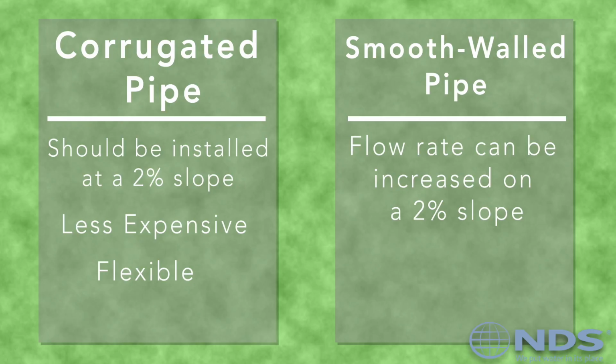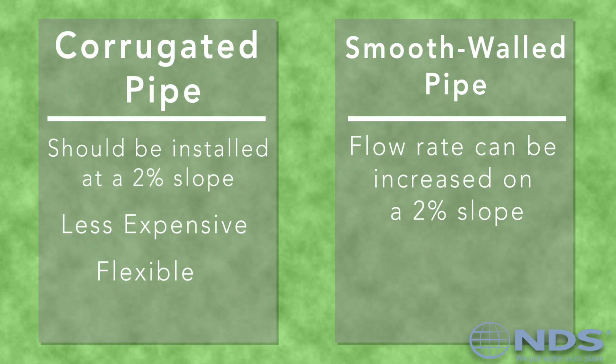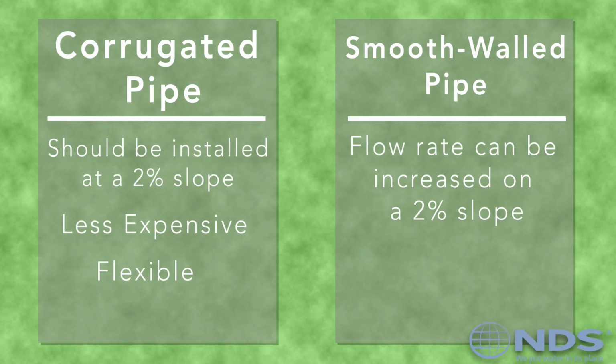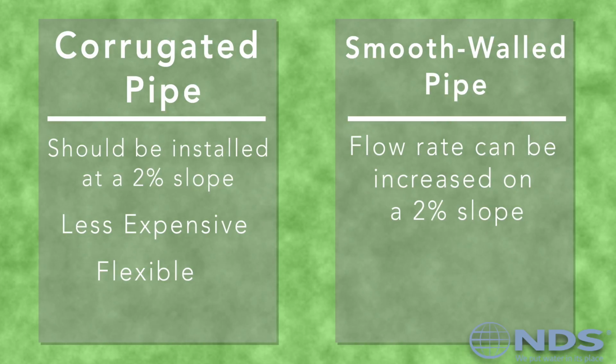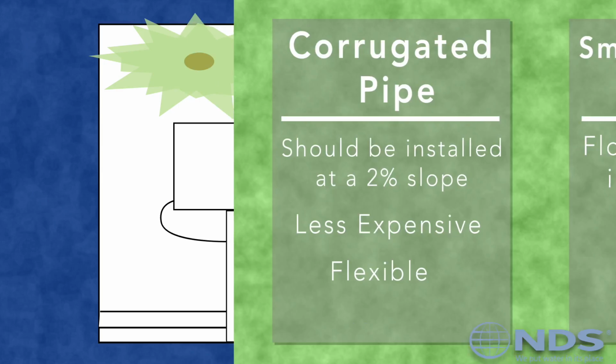But the increased slope requirement and the need for potentially larger pipe can make it more expensive in the end in certain applications, so bear this in mind when choosing pipe for the system.